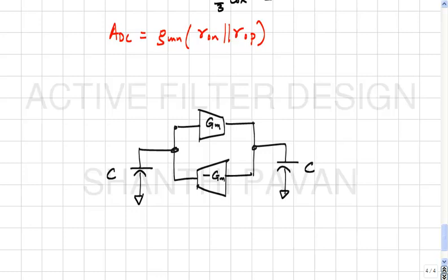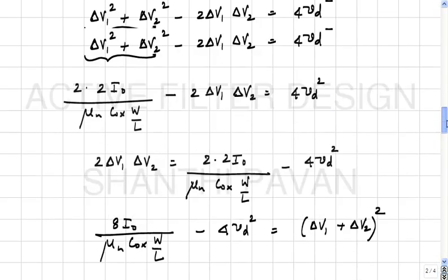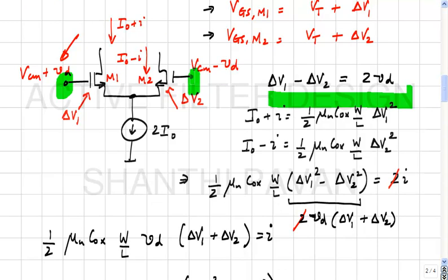All right. So can you comment on the input and output common modes of the transconductor? In other words, we have said that the fully differential transconductor is associated with an input common mode voltage VCM and an output common mode voltage, which is forced to VCM ref by a common mode feedback loop. Now the question we are asking is, does it make sense to keep VCM different from VCM ref? In other words, the input common mode voltage and the output common mode voltage, do you think they can be different? They cannot be different?